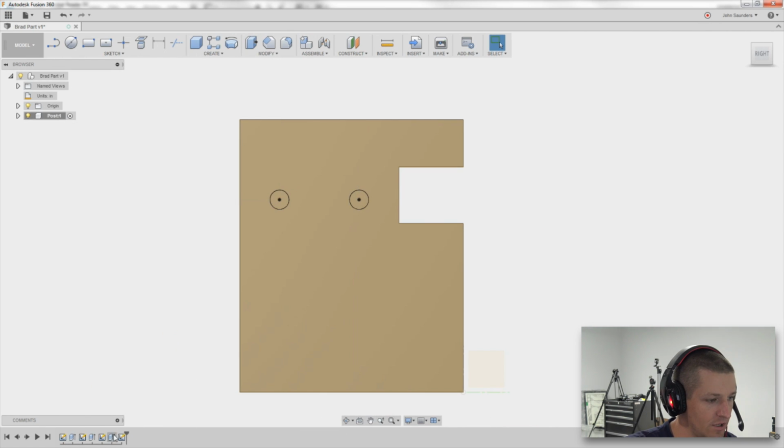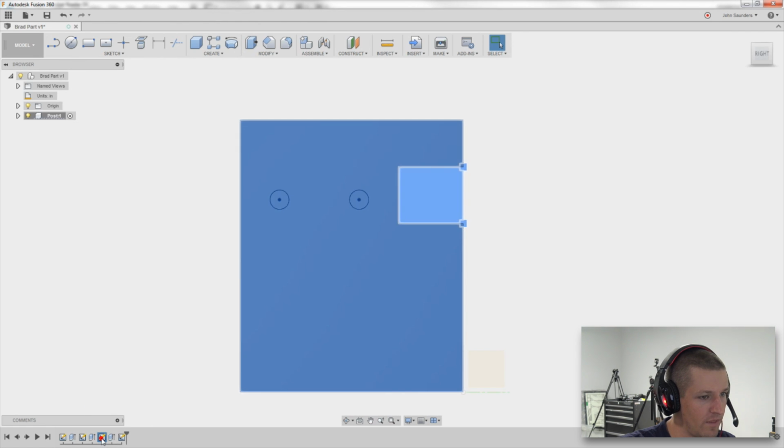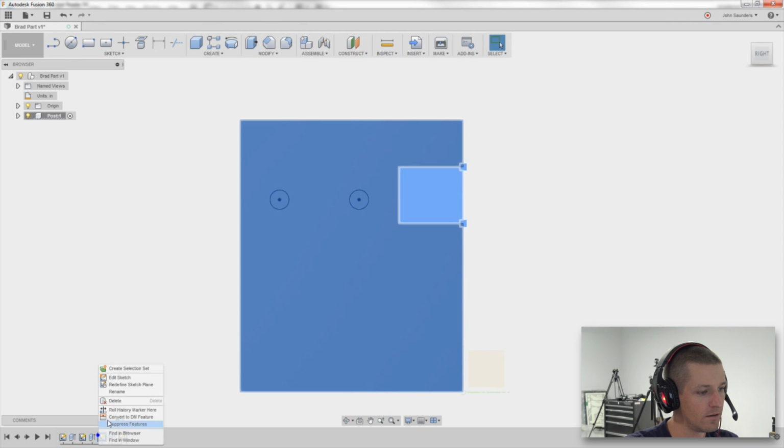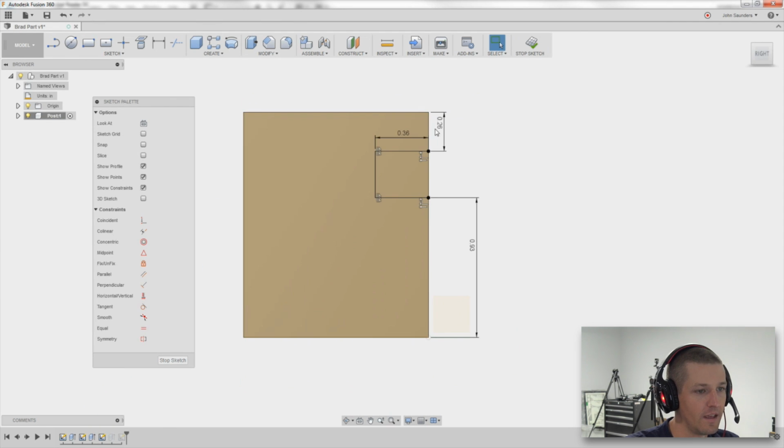So take a look. Easy to fix. Down here in Fusion is your design history. And if I scroll back to, I think it would have been this one, I can right click. See, I can't edit right now. So a glitchy thing, I just have to drag a box and deselect. Now right click, edit. This is wrong.